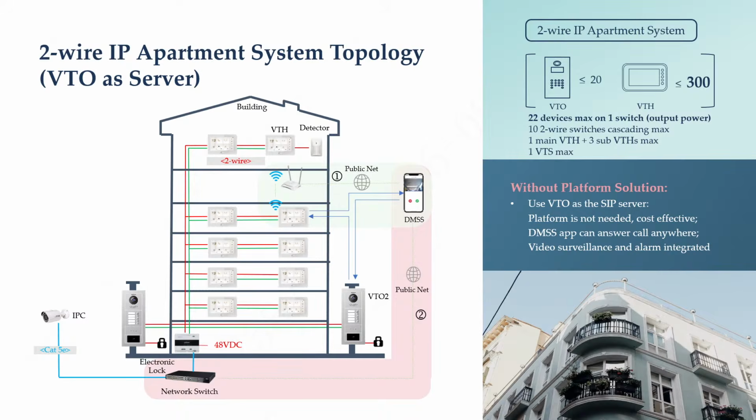Also, when you are installing a system like this, please check the power budget of this device, because this device can handle a lot of power. So when you supply it with 100 watts, you need to know you can get less than 100 watts from its output. So you also need to check the power budget, but it's quite simple.